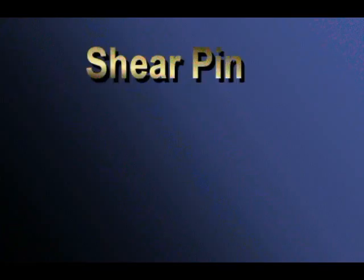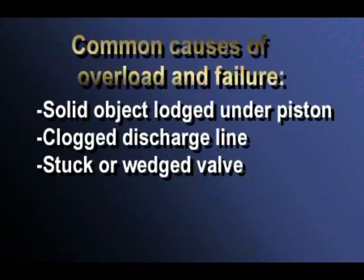The shear pin, which we discussed earlier, has another very important purpose. The primary function of the shear pin is to break to protect the pump from damage in the case of a sudden overload. 3 of the most common causes of sudden overload and shear pin failure are a solid object lodged under the piston, a clogged discharge line, or a stuck or wedged valve.